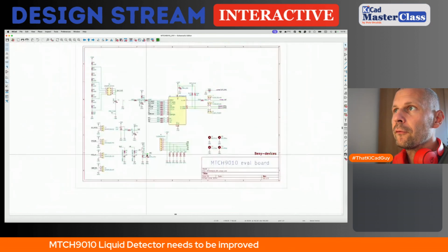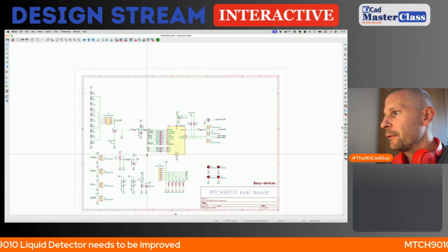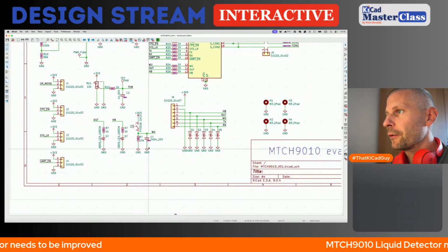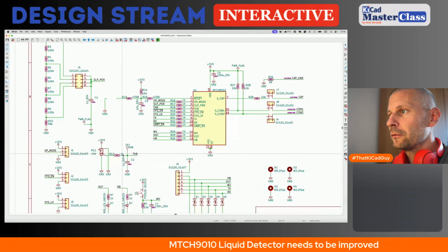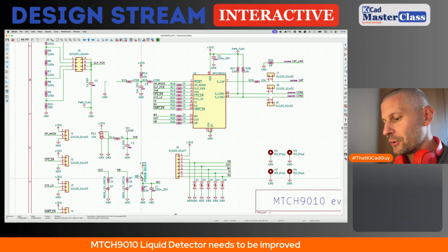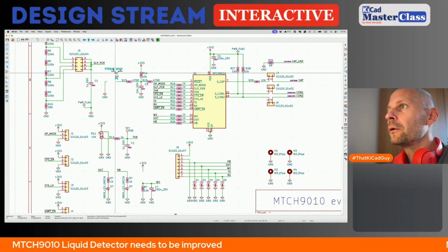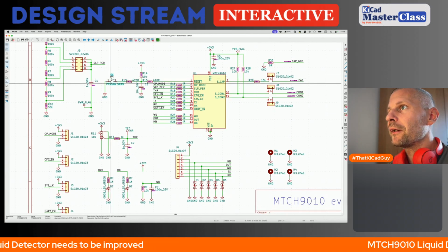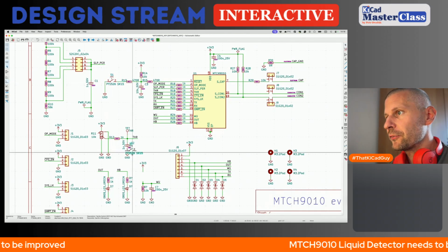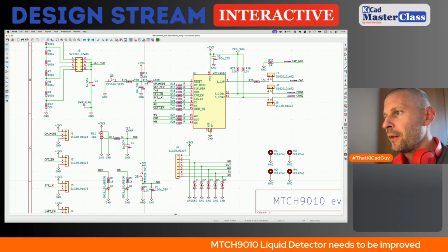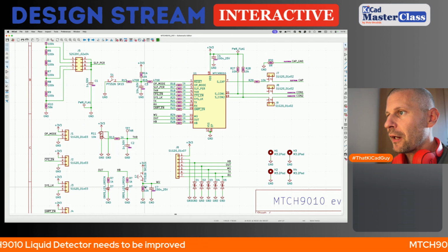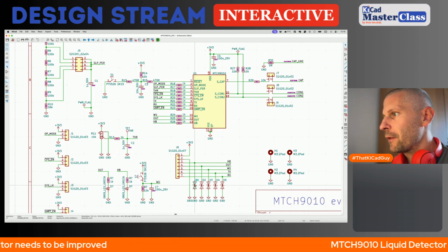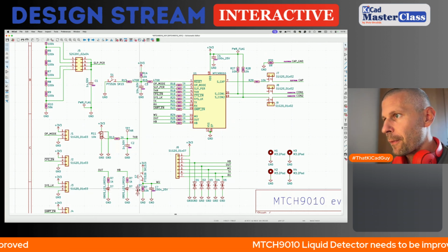And we need an ESD diode for sure here, because I will touch the... I was so clever that instead of duplicating, I just moved the switch from the reset. So okay, and as I said, we need a diode, the ESD diode, protecting the port.